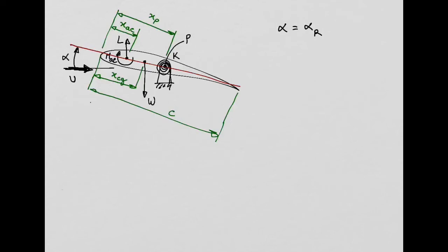But now, in aeroelasticity, our wing will deform. So the total angle of attack alpha will have one component due to the rigid angle of attack from aerodynamics, plus an aeroelastic component, theta, which is the variation in the angle of attack due to the wing deformation.